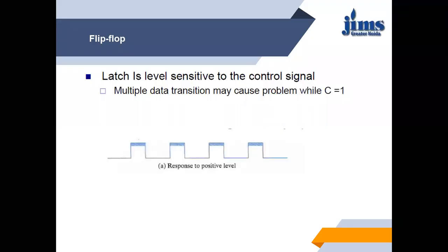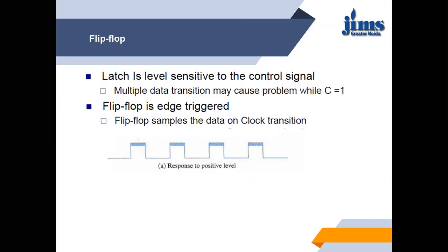So here are the logic level 1. We can see directly that these dark spots or dark levels have been considered as logic level 1. So whenever we are talking about a latch, a latch is always a level sensitive device. When we come to the flip-flop, it is edge sensitive, or edge triggered.